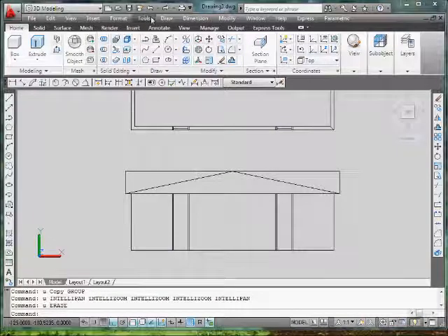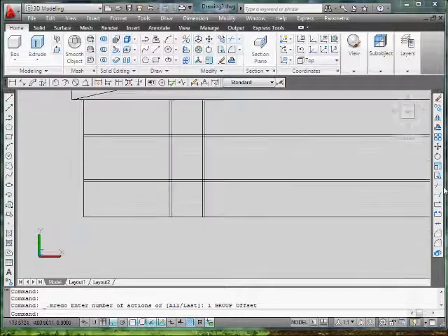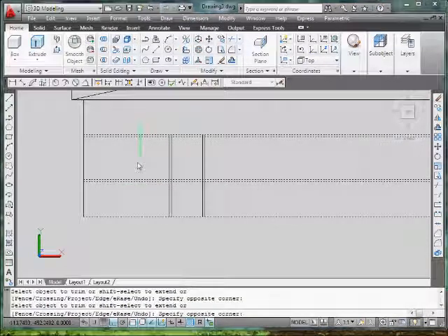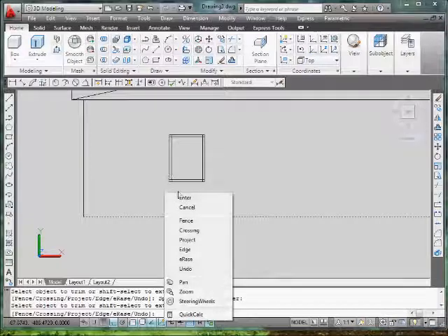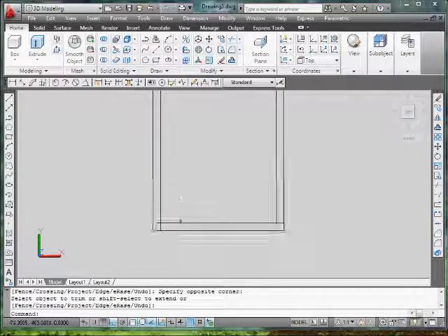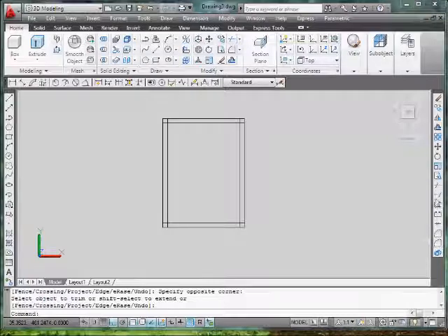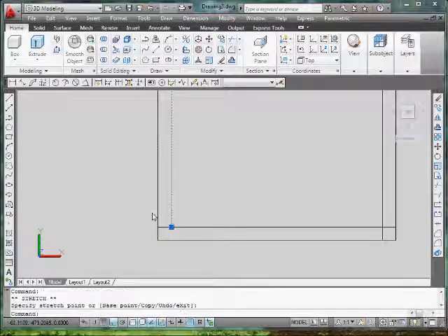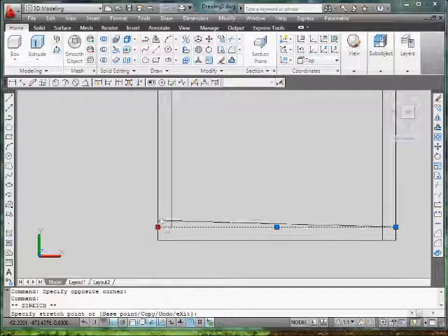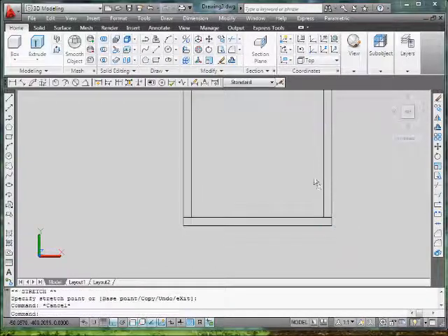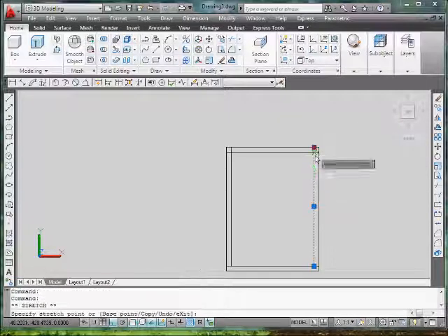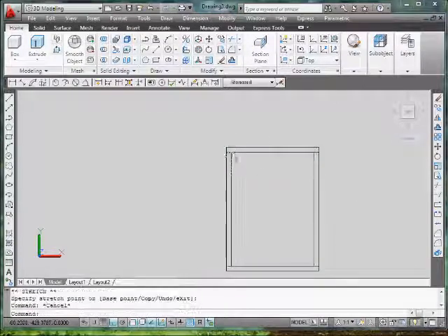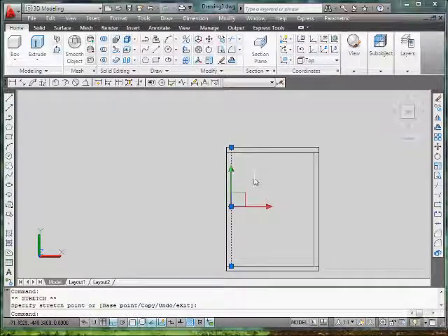Oh wait, I went too far. There we go. Let's say I see the fillet. I have these additional lines. You can do the fillet again. You can use the trim if you really want to, or you can select the lines and just drag them from the blue point to the intersect. Actually, I'm just going to do a design like this. And you can do the same thing with the fillet. If you want to change it to have lines that extend, you could always select the line and click the blue and extend it also. So you can reduce it or increase it.